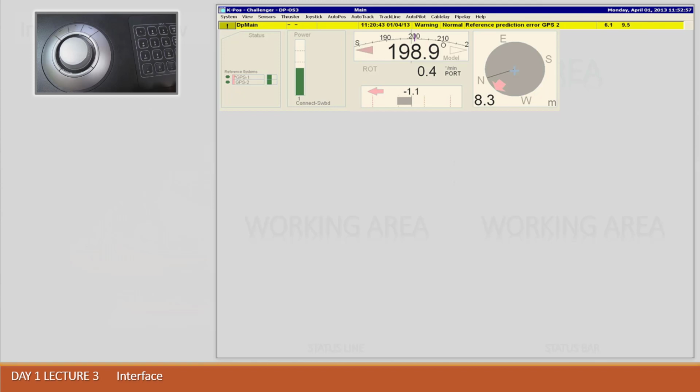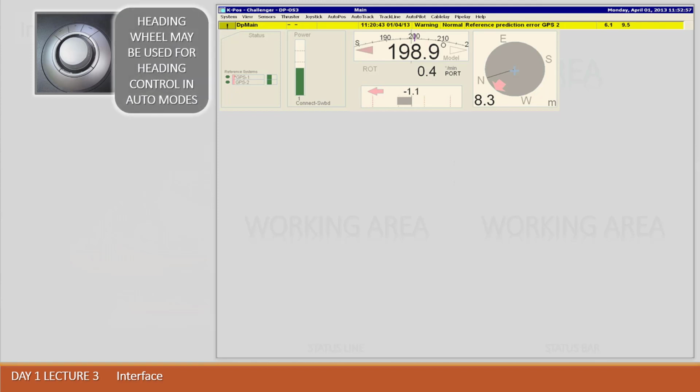Next zone you see is the position indication area. Here the coordinates are shown in the selected datum and way of interpretation. If you put the cursor on top of the position area, and the figures here are highlighted in violet color, then you see all current presetups for all parameters which are adjusted by the user. To reach that, you have to put the cursor on top of the position area, and when the pointing hand appears, you have to press on the position value.